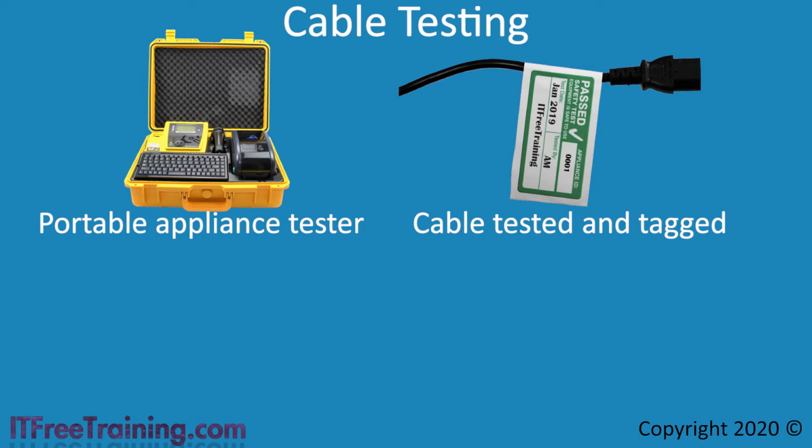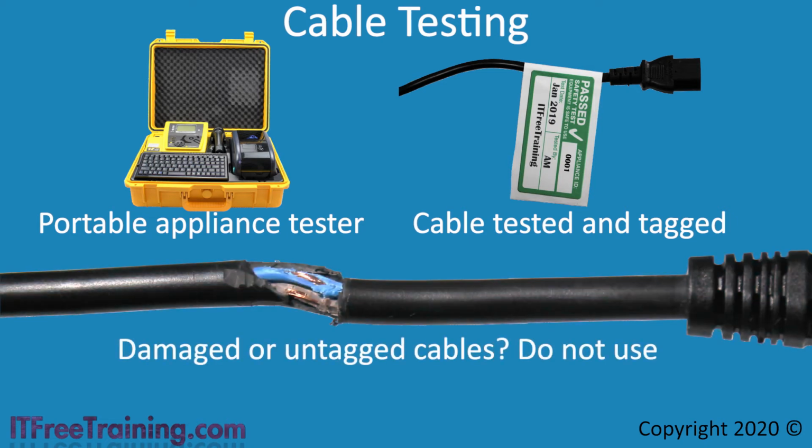In a work environment, if you have a damaged or untagged cable, do not use it, particularly if the cable is damaged. It is not worth getting an electric shock from the cable, or for the cable to damage other equipment, injuring people or causing a fire.